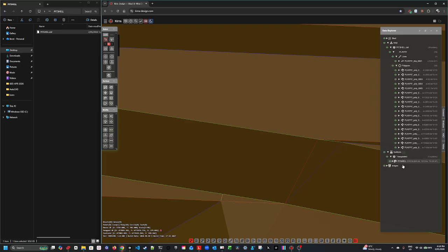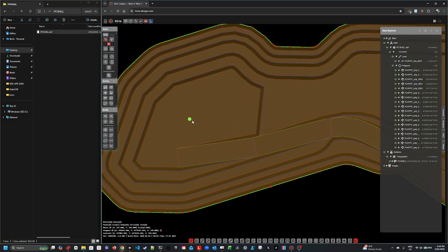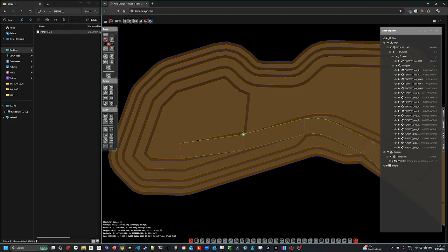Then we've got these various lines now. Depending on the DXF, they may be named or they may not be named. So that's important. But you can name them again. We'll go back to the extents here. Now we can select these from this side here, and we can find these elevations, which one we're looking for. Well, we'll call this one ramp 1.